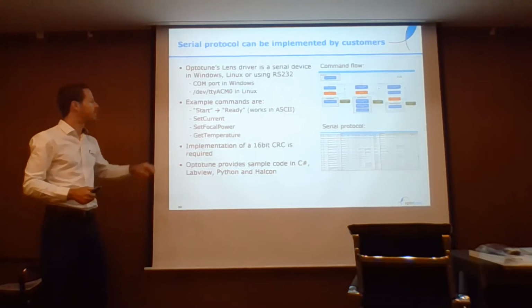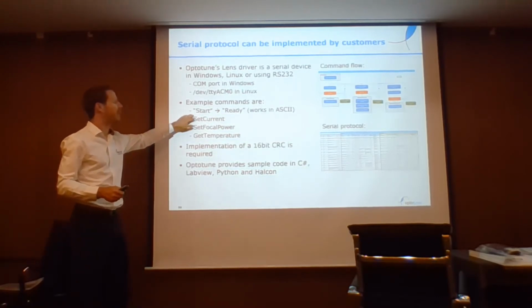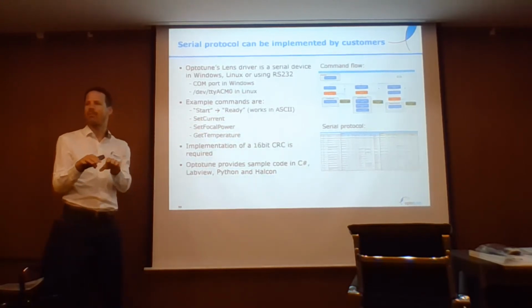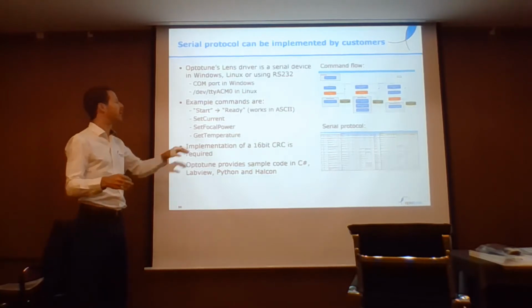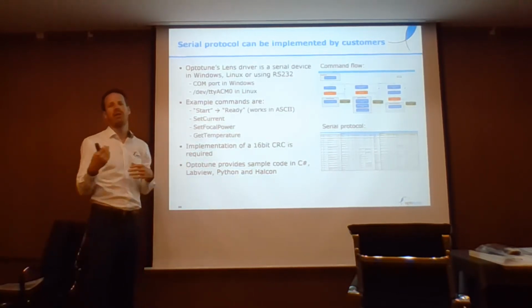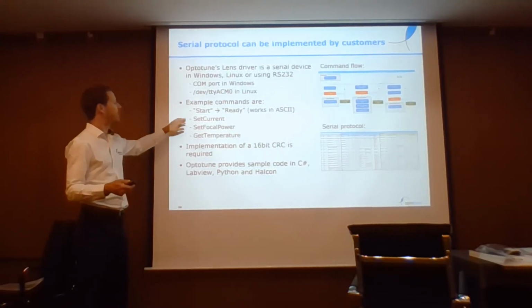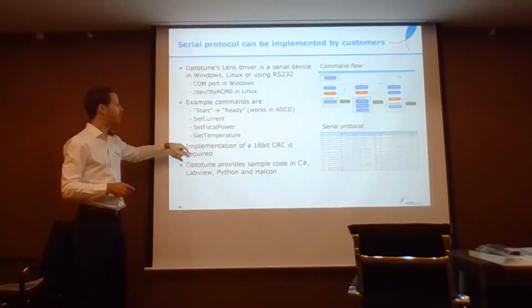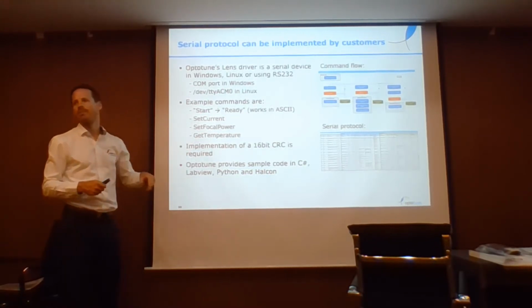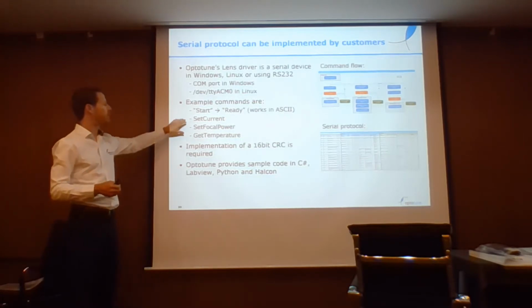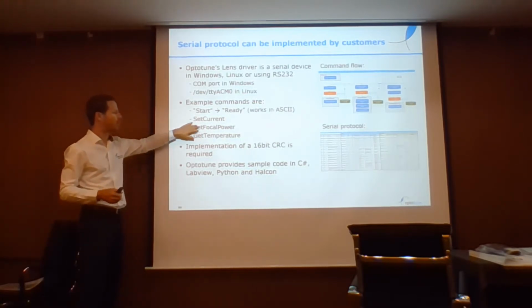The very simple command is start. It actually works in ASCII, so you can type start, send, and then the driver replies ready. This is a very simple handshake just to check the connection. And then there are commands for set current, set focal power, get temperature. There are a few more commands, but these are the most important, specifically set focal power.